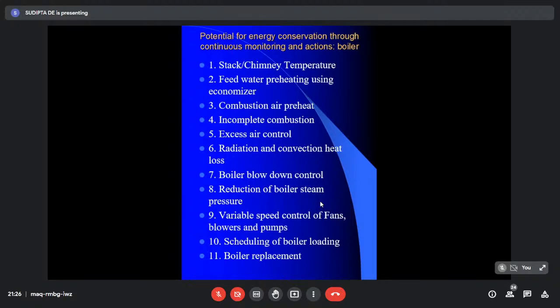Okay, here in short, this scheduling of boiler loading point is not related to a single boiler. In many applications, there are multiple boilers simultaneously providing to a common steam demand. Say in many of the food processing or chemical processing industries, this has happened. And then what happens when the load demand decreases? Then there are two options: keep a part load or lower load for each of these boilers to accommodate that lower load, or you can just shut down one of the boilers, keeping the other boilers operating at full load. Because operating at full load always leads to better efficiency.